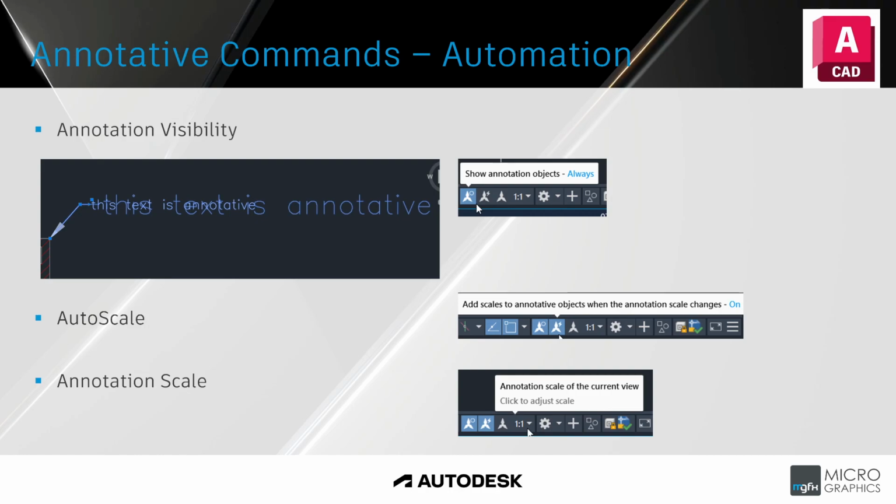And you see that my annotation is not there, it won't be visible. So let's go back to the model space, select auto scale, and change it to that 10:1 or 1:5, whichever one you've used in your paper space, and then it'll start populating all the annotations in the viewports that you've created in your paper space.